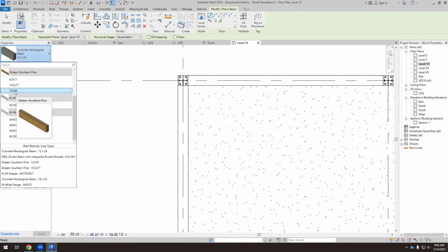Why? Because when the beam is resting on columns, the deformation of the beam is going to be like this. So we need the maximum amount of material at this section. And where do we have it? It's the moment of inertia, but it has to be this way. So it's a terrible mistake if we have a beam and we place it in this direction.